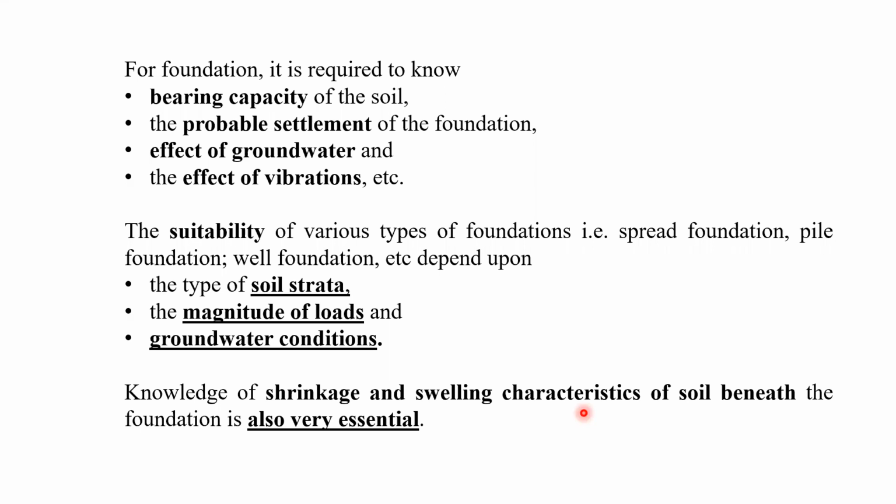Suppose you do not know which type of soil is there at the site. Suppose it is a black cotton soil, which may swell or shrink depending upon the season. So these points should also be studied. The study of soil should be carried out. Otherwise, there is a chance of geotechnical field problems.